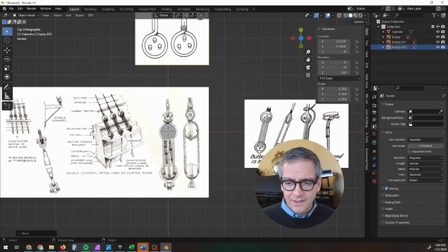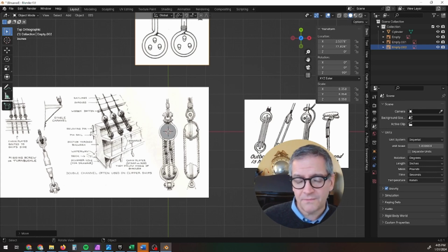So Jack Coggins here, these bindings, these are iron or steel. These are for a clipper ship, and he's actually talking about clipper ship rigging here. These things that stick out from the side of the ship that hold these away are called channels, and these are called chains, and these are called chain plates down here. So often you'll hear about things being stored in the chains of a ship. That means stuff that's tucked in under here. It was often spare masts, spare pieces of rigging, spare spars thrown in under here because it was a great place to store stuff.